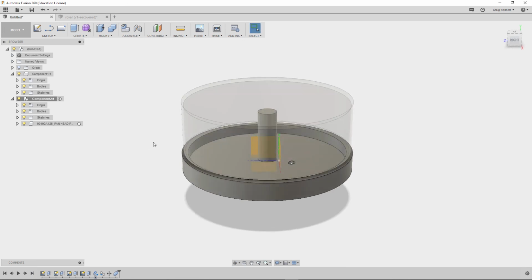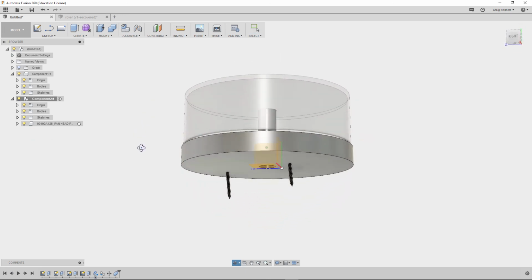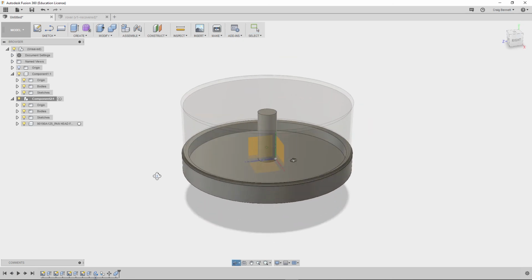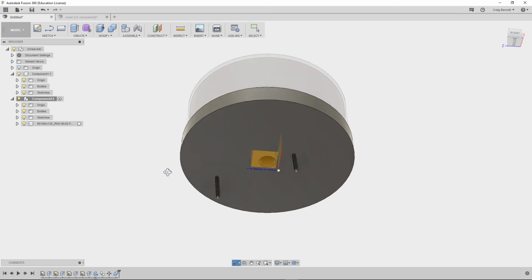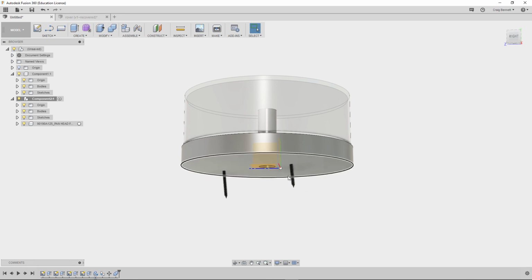But anyways, hopefully this has helped you out and get an understanding into this, and that way you know not only how to make basic things like this, but you can actually know, okay, this is the proper screw hole size for this. So if I got a bunch of these type of screws, I know I need to make the screw hole this big in order for this to work, so I don't have to cut any plastic or whatever. So as far as that goes, hopefully that's helped you out.